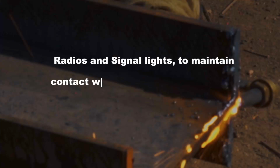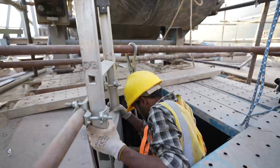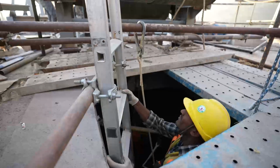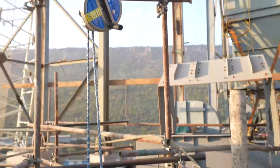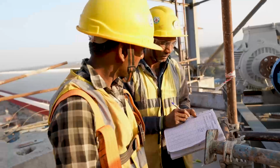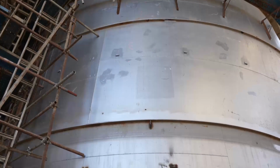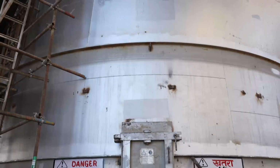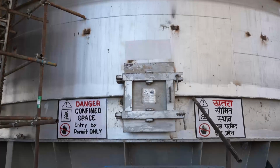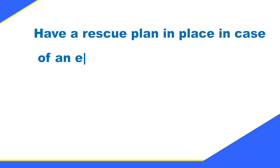Use proper lighting and communication equipment such as radios and signal lights to maintain contact with your colleagues outside the confined space. Always work with a buddy or a team in confined spaces. In case of an emergency, your buddy or team can assist you or alert others. Follow proper entry and exit procedures when entering or leaving a confined space. Keep the entry and exit points of the confined space unobstructed to ensure a quick exit in case of an emergency.